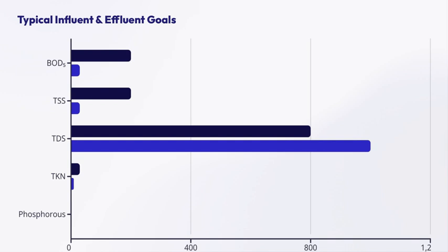Second, they target the removal of dissolved organic solids, which are a major source of pollution if discharged untreated. The goal here is to reduce these substances to levels that protect water quality downstream. Another key point is the reduction of pathogenic microorganisms. This step is crucial because it helps prevent the spread of waterborne diseases, safeguarding public health.